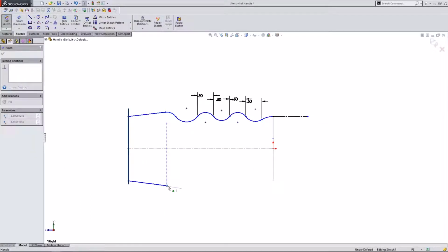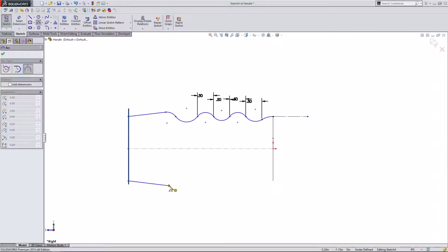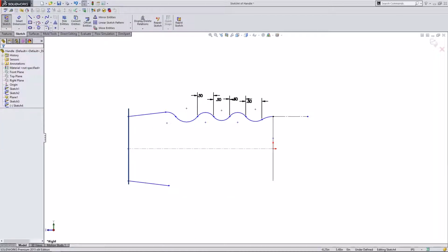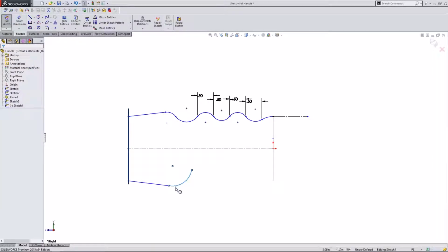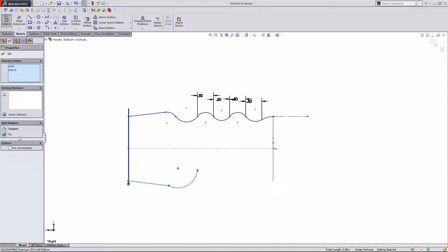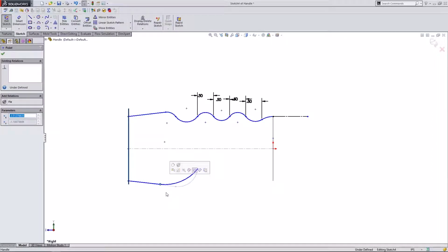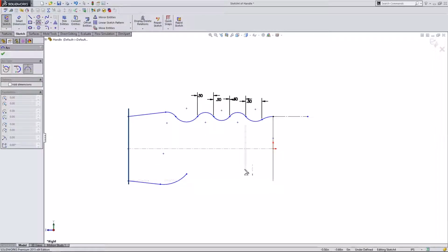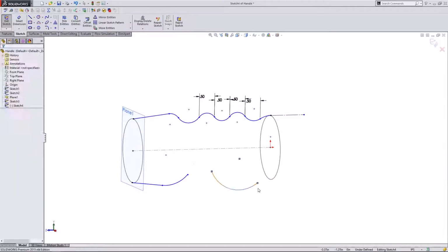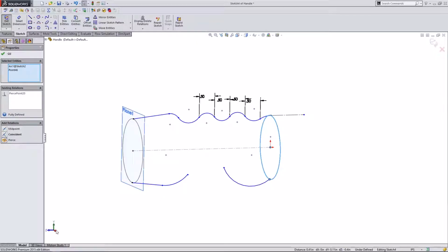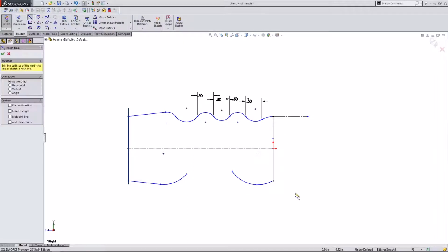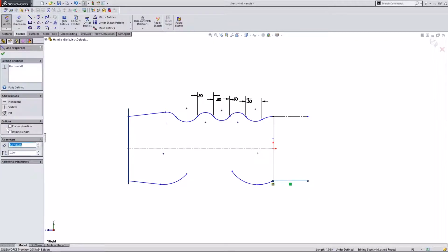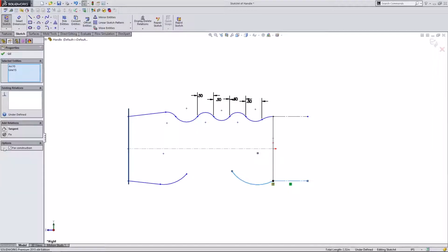And now I can create the rest of the shape here. I'm going to create an arc. This arc, probably want to come up like this first. Make these 2 lines tangent. And from here, I can create another shape that's going to start on that circle. So I'm going to drag it out first, click on the point, click on the circle, pierce, okay. And from here, I'm going to do the same thing I did in my first sketch. I'm going to come up here, make a line, bring it out, make it for construction, select the arc, select the line, make them tangent.